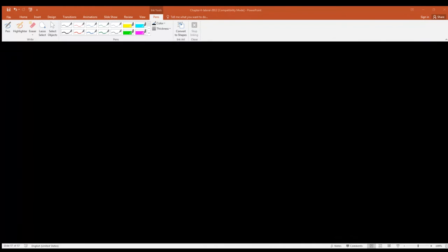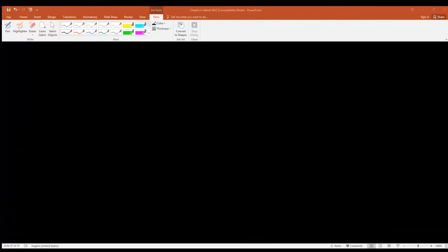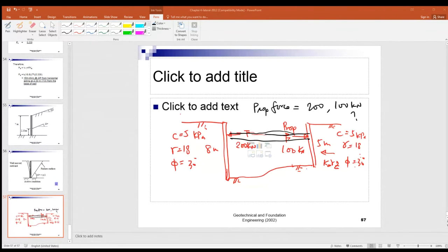And anything in the upper part sliding down over the bottom part, that is a shear case. So that's why we have to study the shear strength of the soil, because soil always fails by shearing. In other words, the soil mass will always slide against another soil mass. So that constitutes a shear between the two masses of soil.